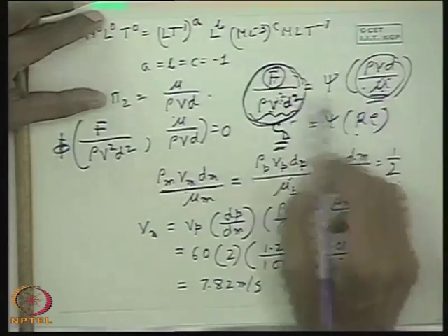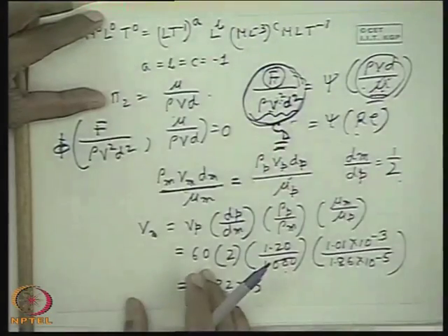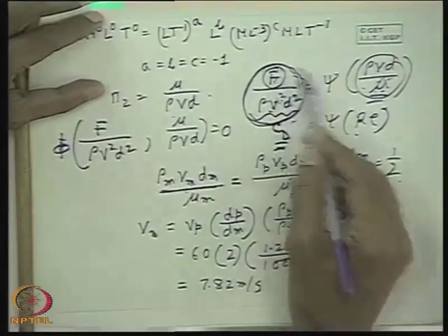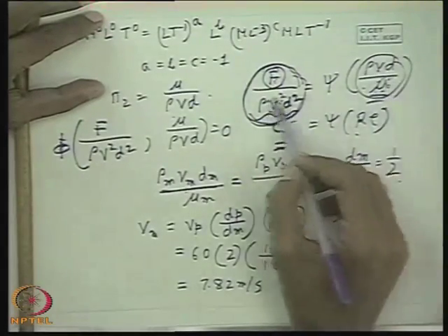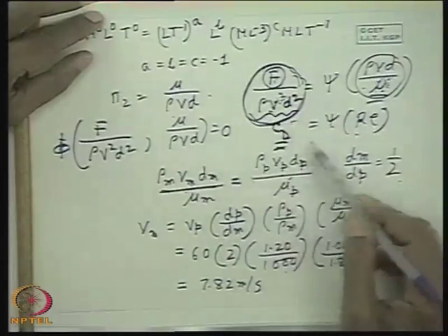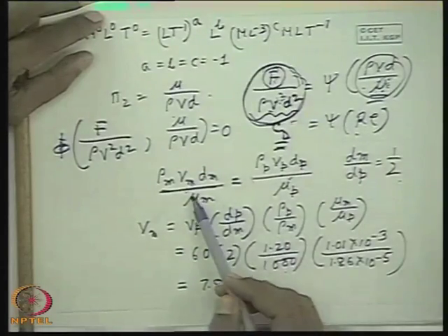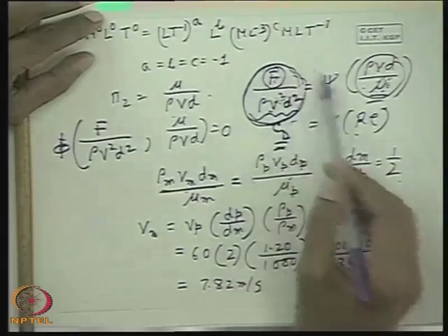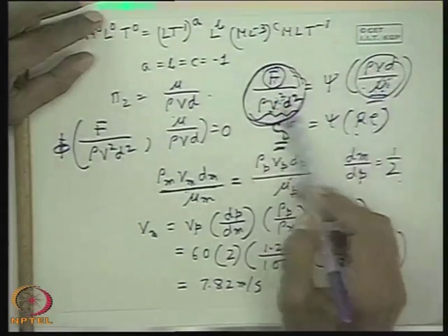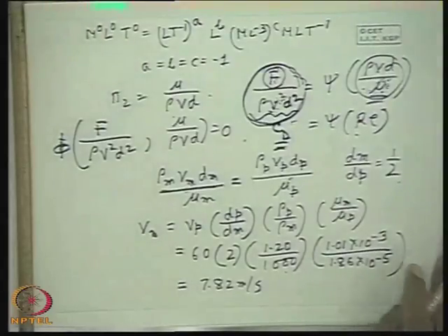This cannot be done. This has to be done either by a theoretical analysis or by doing experiments from the empirical points by regression analysis. Otherwise, the explicit relationship is not possible. But in comparing the results from model to the prototype, it is not necessary to have an explicit relationship. If we know the pertinent dimensionless terms governing the problem, it is all right.